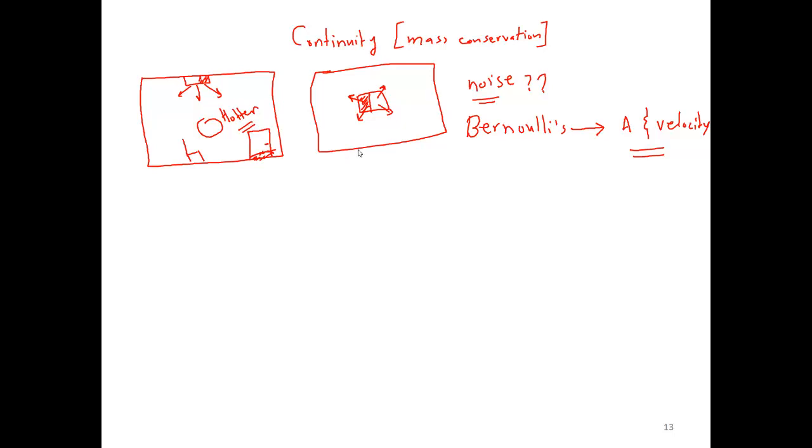It's a closed room, very well sealed, and then all the air keeps coming in, and it starts becoming pressurized till the moment where the pressure in the room is higher than the pressure inside the ducts or the supply, and then no more air can get into the room, because the pressure here will be resisting the air from coming in. And then you don't have enough cold air coming, and the temperature of the room will start increasing, and then you'll start having this warm sense.